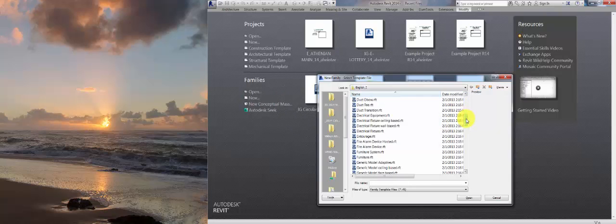When you go down to lighting, you'll have the option of doing something that's ceiling or wall based. Never use ceiling or wall based. If you want to use face based, you can. And it might be difficult at some times to find the right template. You can always use generic model and change the category afterwards if you find the templates limiting.